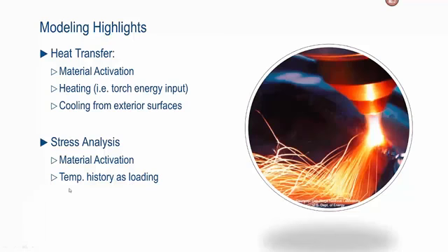In the stress analysis, of course, you prescribe the temperature history as loading, and that temperature comes from the heat transfer results.